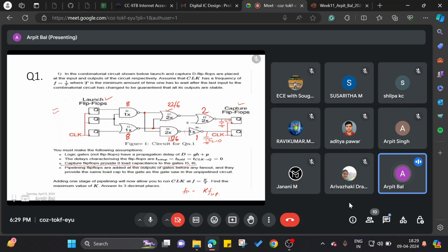Okay, I have noted down the delays on top of each gate. So from there, can you tell me which one? Sir, first one. Okay, so first one means I1, I3, I5. Yes. Yeah, correct. Because that is the path taking the maximum time, that is the critical path. Okay, I have put it in dotted lines.